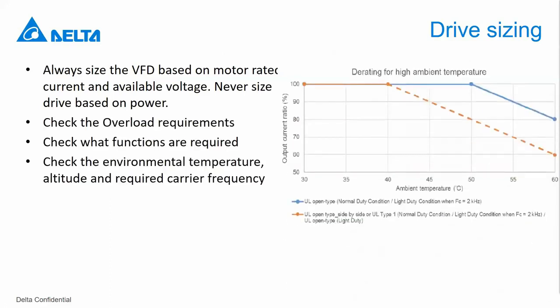You might have to derate. Derating means that you select a drive of a higher rating than that of the motor. Some typical conditions when you might have to do this are when there is a very high overload requirement, or when there is a high temperature.